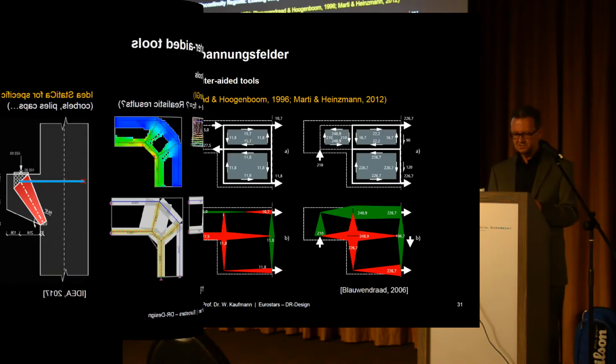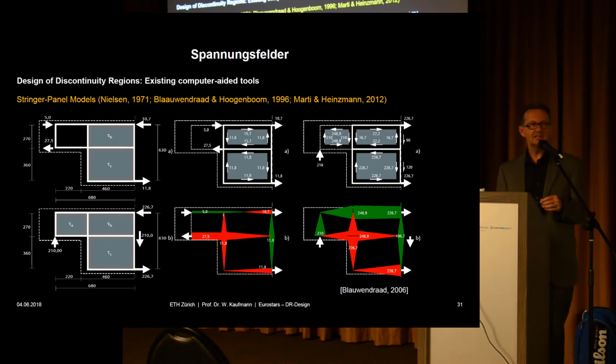Then, one that you certainly know even better than me, the stringer panel method, developed and implemented by Professor Blaauwendraad and Dr. Hoogenboom. I was saying it more or less. I'm sorry, my Dutch is really limited even after the introduction. I can understand some, but my pronunciation is certainly awful. And so they developed that, and my predecessor also had a project. That works really fine. So you model the stringers as tension cords, and you model the panels using a suitable panel model, and you get very good results.